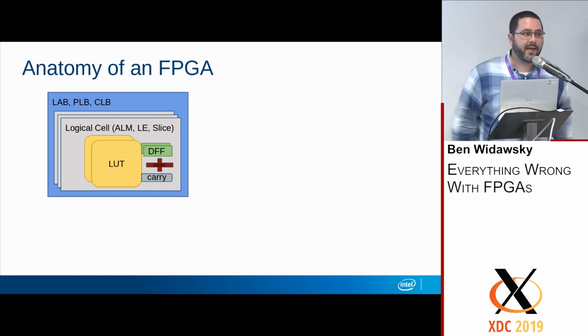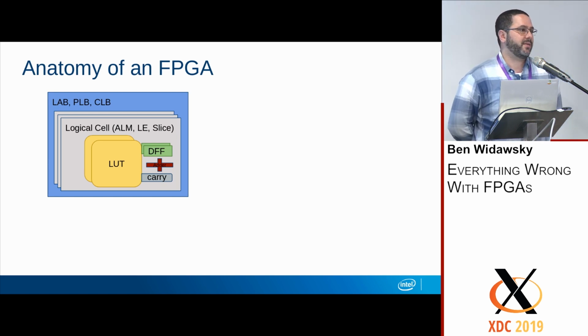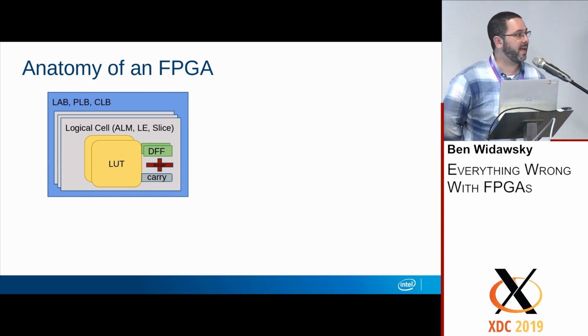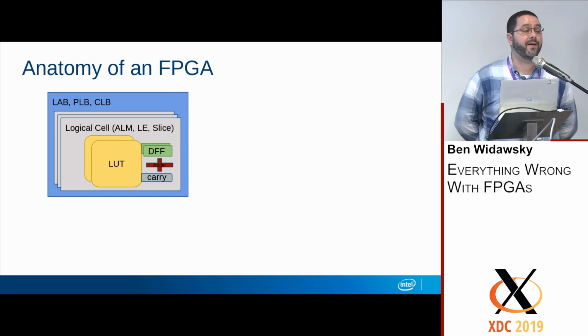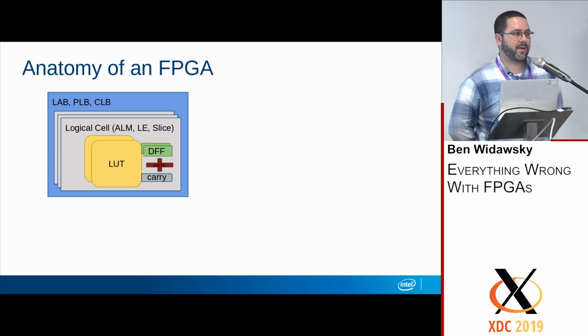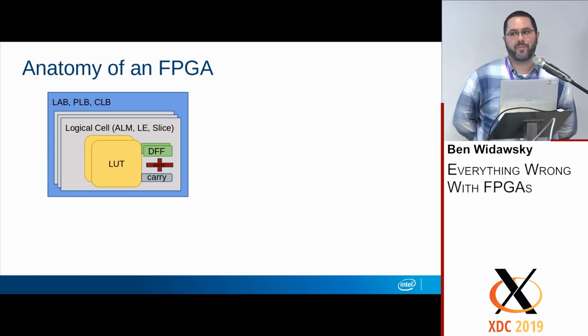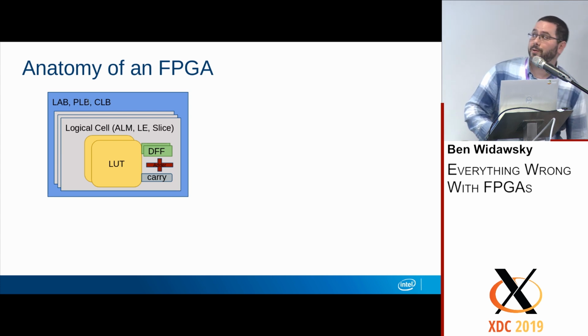So as I was saying, most FPGAs aren't really just lookup tables. They're a lot more than that. You'll have flip-flops and adders and carries, and those carry chains. And those carry chains are generally meant to make speedier arithmetic because as the units are laid out on the chip, you might not have direct access between any two logic cells.